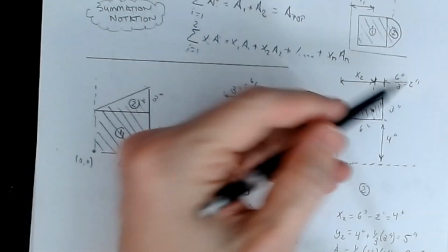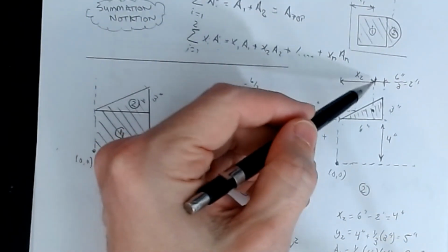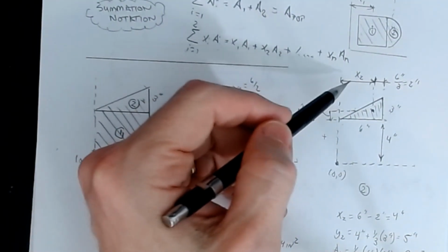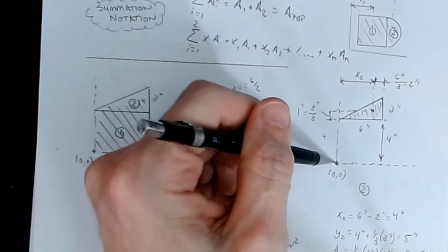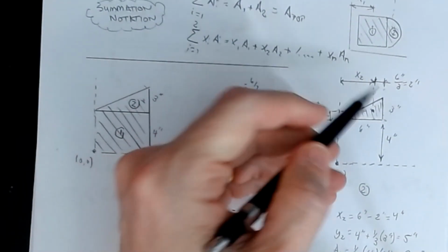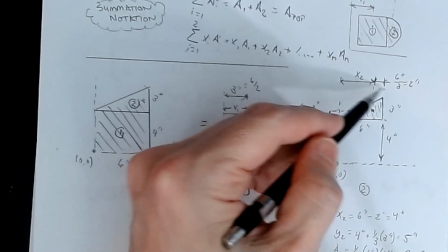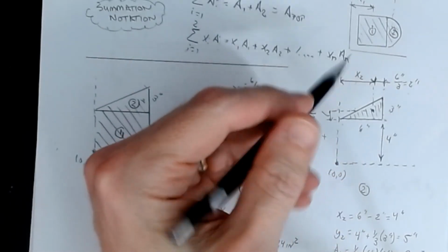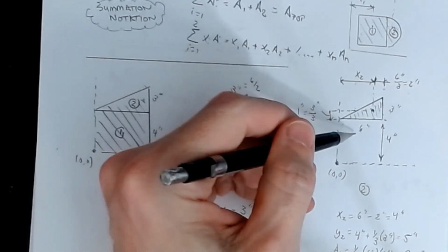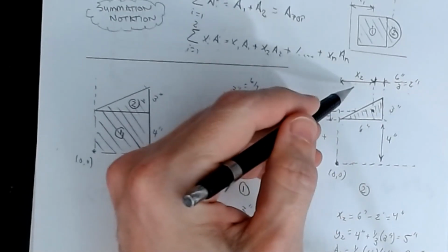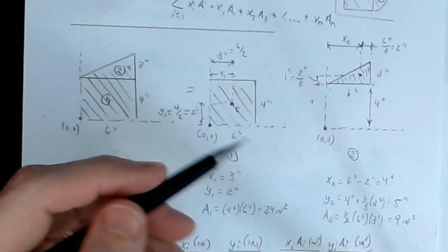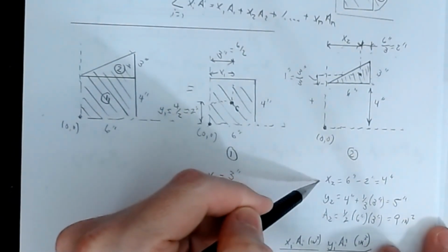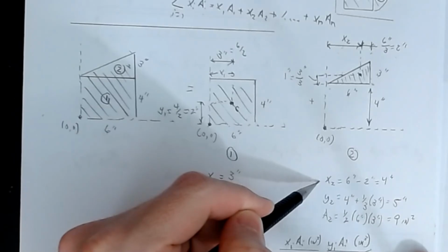Okay, will get me that one, and then my x2 is whatever is left, and so again, we have to measure our x value from my centroid reference. Okay, so even though I know that the x bar for a triangle is from the high end, this number, okay, I've got to shift that and make x2 as being 6 inches minus 2 or 4 in this because of the orientation of the triangle. And that's what you see I've done down here. Okay, so you got to kind of watch the orientation, which way this thing is aligned and so forth and so on.